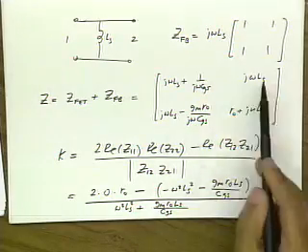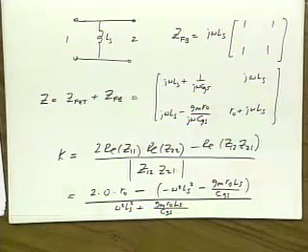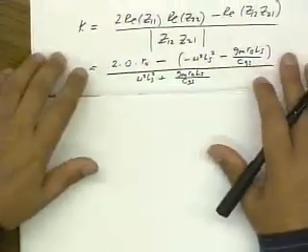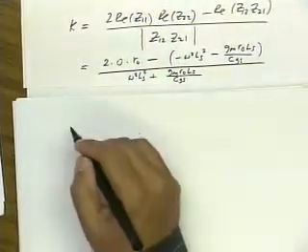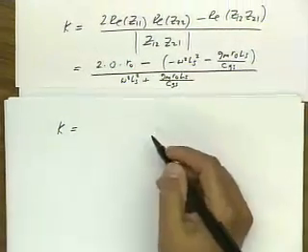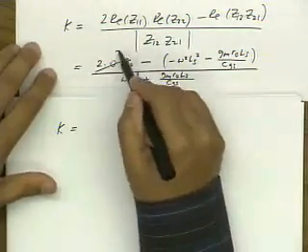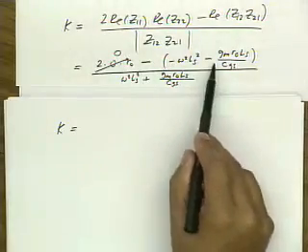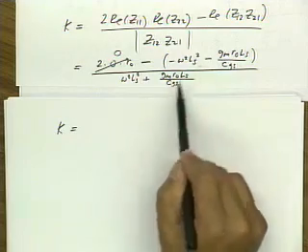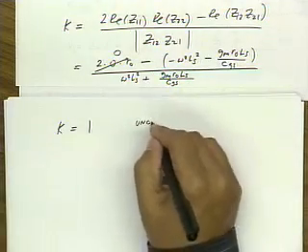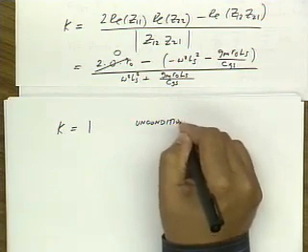Okay, so it's just the magnitude of this product, and that's what the magnitude of the product is. Okay? So that's our K factor. And what we'd like to see is under what conditions is K greater than 1? Well, take a look. If now this term is all 0 here, and this term becomes plus, and so now we see this ratio is exactly equal to 1. So this is unconditionally stable.